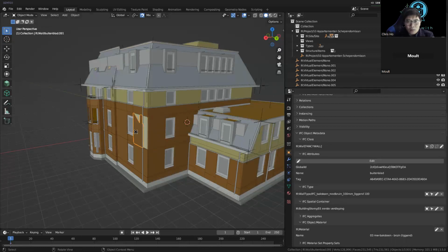Oh, it's really easy to amend it to user defined. Because if you're going to do it in the authoring software, there are so many things that you need to set up before you can actually make it user defined. This really simplifies the workflow entirely, just by clicking and editing, and that's it. That's your user-defined name. It's fantastic. Correct. Because it's native IFC. It shouldn't be difficult. It's just an attribute.